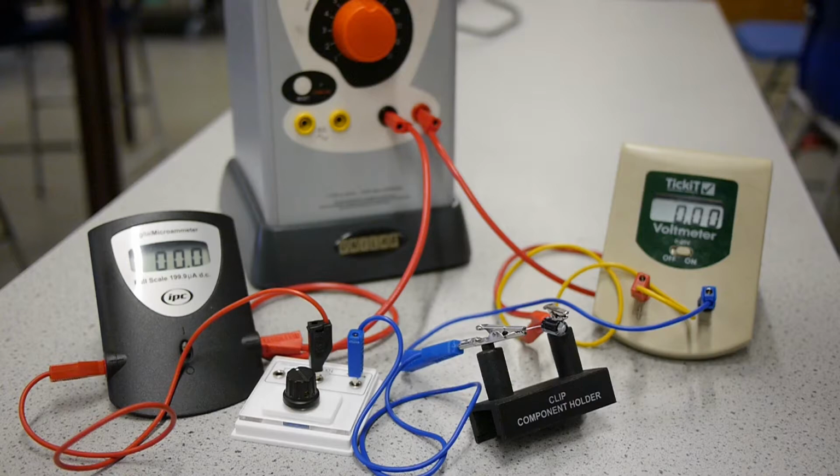The current here that's going to flow is going to be pretty small, and then we've also connected a voltmeter across the capacitor. We're going to turn on the power supply, and what we will see is that a current begins to flow. A current of about 60 microamps initially flows in the circuit, and then as time goes on we'll see the current drop, and we'll see the potential difference across the capacitor rise. Now let's try and think about why that is occurring.